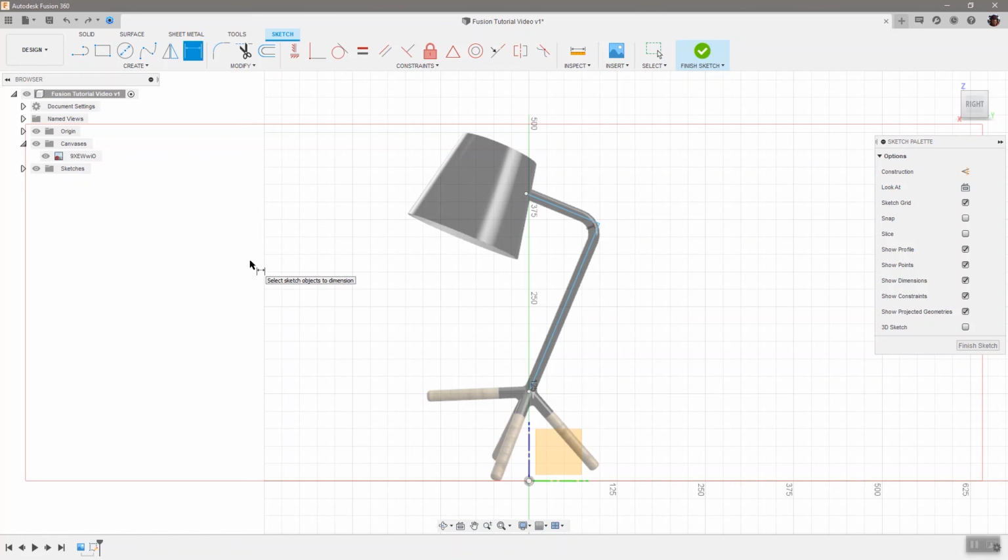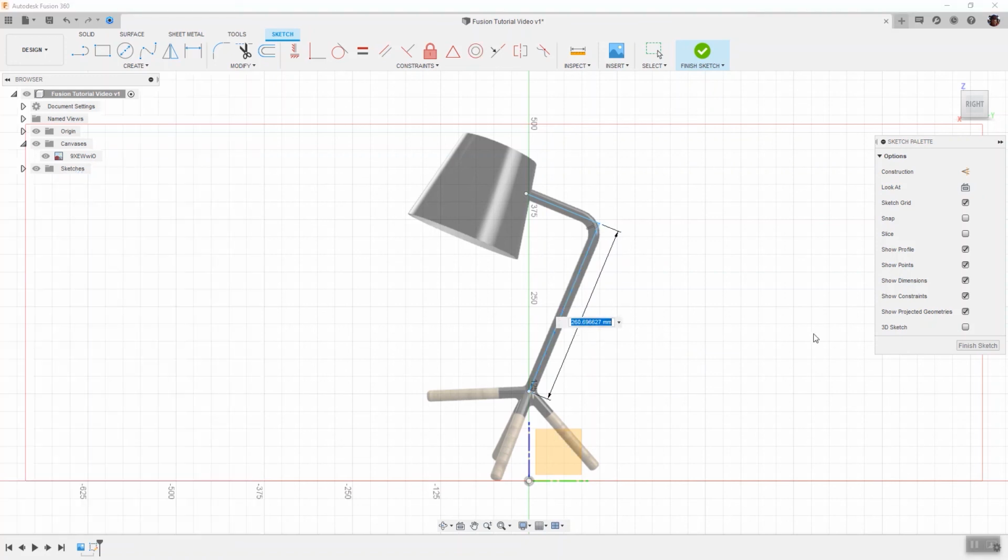And in this particular case, I'm going to give a linear dimension to this line. Now you'll notice, depending on where I place my mouse, that positioning sort of changes, and I want to make sure that I get that angled one. So make sure you move your mouse around till you get that one. And if you don't like the way it looks, no panic. We just have to click it, and then I'm not pushing my mouse right now. And then when I push my mouse again, it places it.